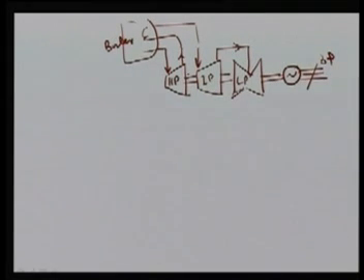So, we have the shaft, and all of these, the high pressure turbine, intermediate pressure turbine, and low pressure turbines, are on the same shaft where your alternator, a synchronous machine, is connected. So, we have here the 4 rotating masses. All these 4 rotating masses are connected with the shaft, and that shaft has some stiffness constant, it is not infinite.